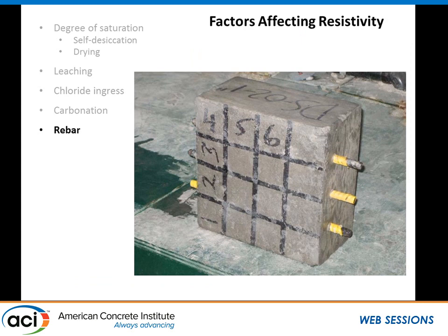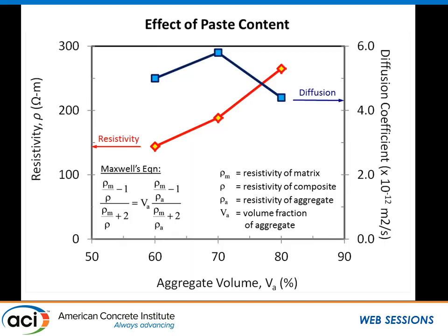Finally, another thing that's going to impact your results to a great extent is embedded reinforcing steel when you're making field measurements. Very, very significant impact. Very, very complicated because it's going to depend on the geometry of your reading and the geometry of your steel. If you want to find out more about that, read Dave Smith's thesis because I don't have time. Finally, the last thing, and I promise you it is the last thing, another thing that